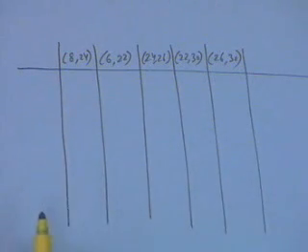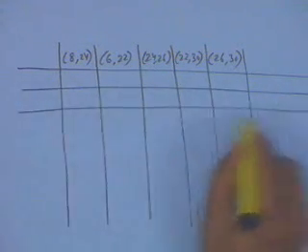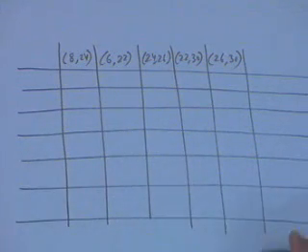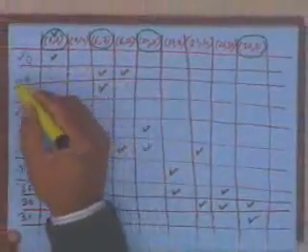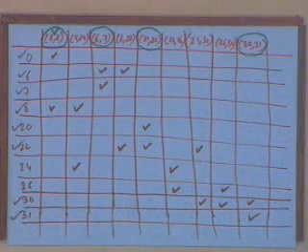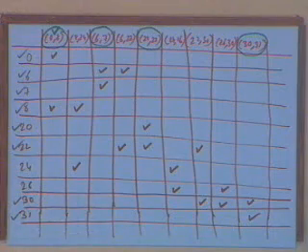Four of them are essential, and these five are non-essential. And I will also eliminate those minterms which have already been covered by those essential ones. So if you now look at this, 0,8 covers this, and it also covers this. 6-7 covers this and this. 20-22 covers this and this. 30-31 covers this and this. So the only thing that is left uncovered is 24 and 26. So only these two rows are required.